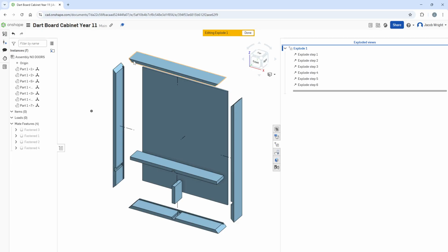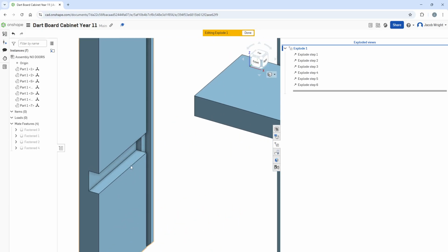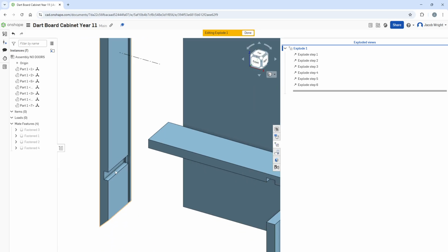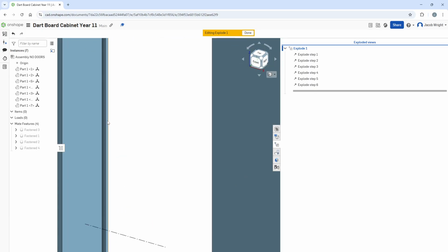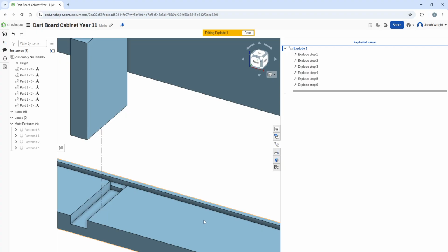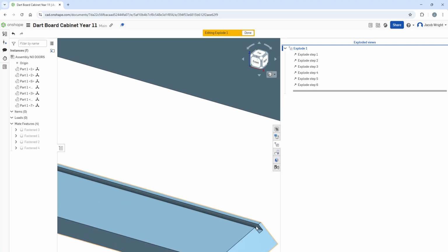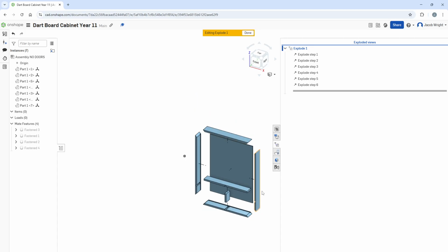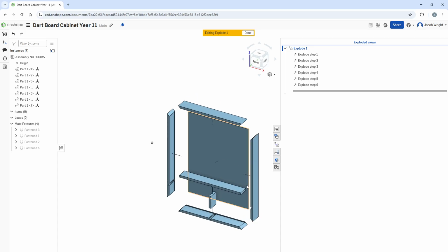So we can see here our miters. We could draw some details into those miters, like dominoes on those angles, to show that that's what's being used in that particular instance, even if it was just the holes. We can now see pretty clearly how the housing works. If you had a stopped housing, you'd also be able to clearly show the stopped housing. And we can also see the groove in this particular instance in the pieces for the backboard to sit inside. So it's showing off all of the joinery that we couldn't see when the component was fully assembled.